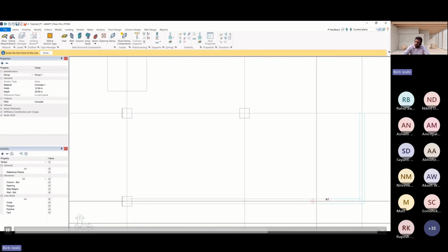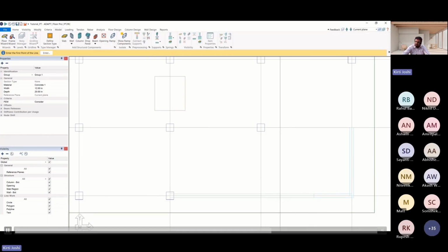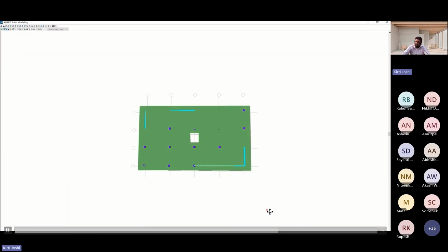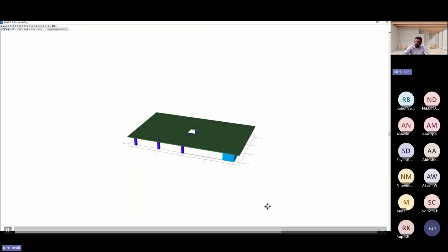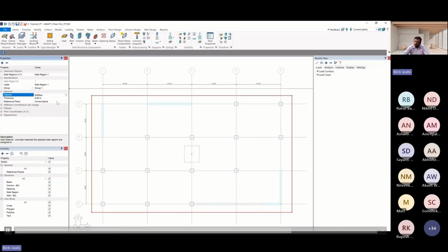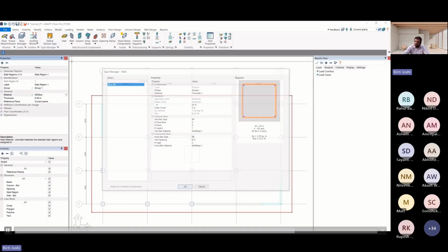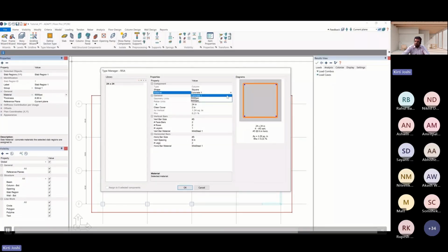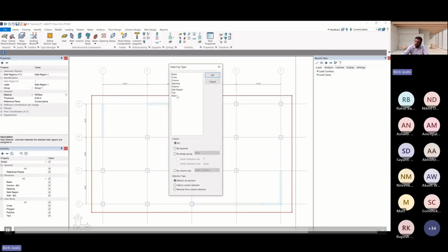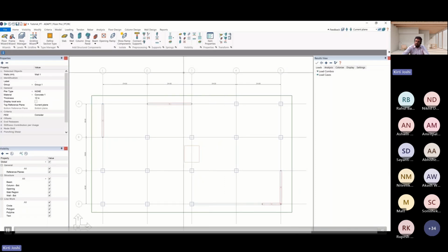So like we have created the beams as well. Now I have already used the transform feature for the columns and the slab, and used the beams for this, so that you can get the 3D models. And after that, you can easily modify the properties of your slab or even the column or even the wall that can be available from the left-hand side. And you can assign the materials, like you can assign the section size and everything from this property toolbar.